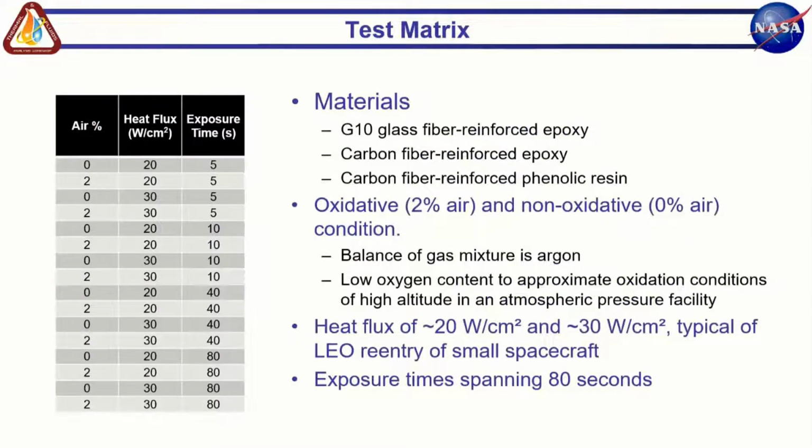So our test matrix consisted of three different types of fiber reinforced plastic. We used a standard G10 glass fiber reinforced epoxy, which you might find in circuit boards most commonly, and a carbon fiber reinforced epoxy, and a carbon fiber reinforced phenolic resin. We used both an oxidative and a non-oxidative condition, where the oxidative condition had a mixture of 2% air and balanced argon.